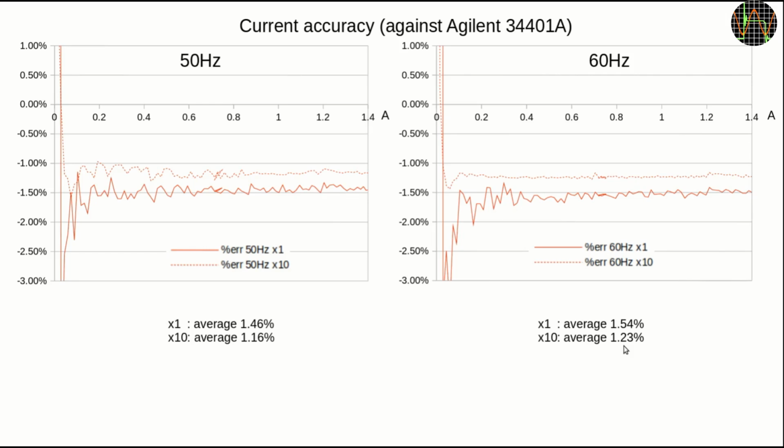I should also point out that the chip expects to be calibrated for the specific current transformer used. It has correction registers for the current and the phase shift caused by the transformer itself. The fact that this kit comes with a choice of 2 different transformers makes me wonder which, if any, was used for calibration.